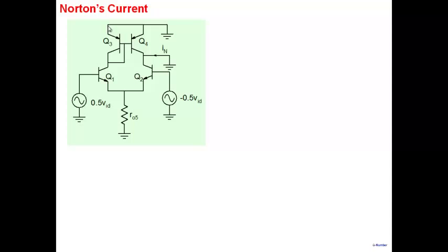If it's a very small resistor between this point and this point here, 1 by GM, which means that the voltage developed at this particular node will also be very small. If the resistance between this particular node and ground is very small, then whatever current flows through this particular resistor, the voltage at this node also will be very small. Now, if the voltage is very small, to the first order approximation, you can assume that this node is also very close to ground.